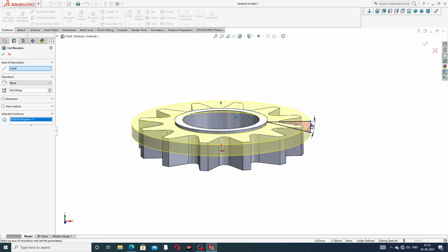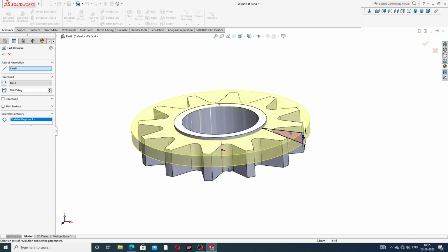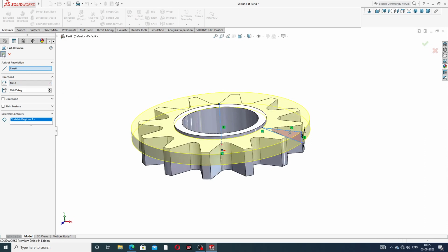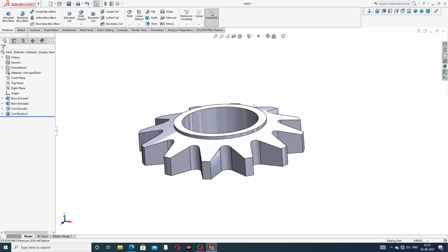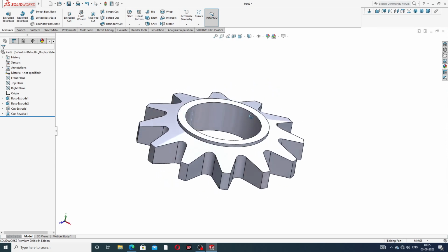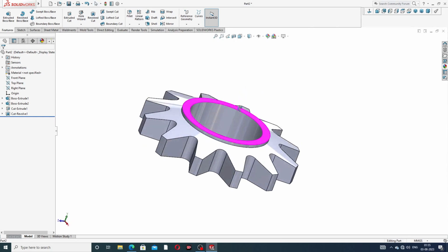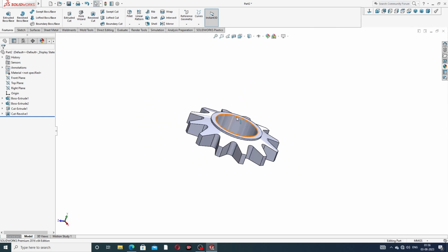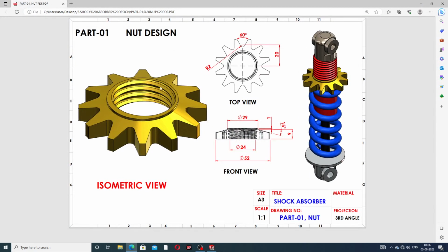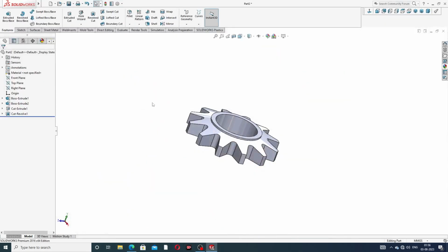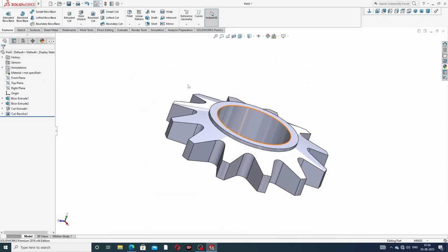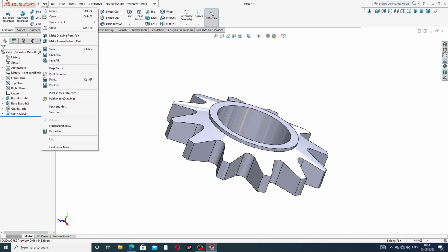The center line is perfect, and use a revolve cut. Revolve cut is applied here, and this inclination of 15 degree is cut here. All is perfect. Next, use a thread. Thread is very useful, and it is easy to use. First, a part is drawn here.